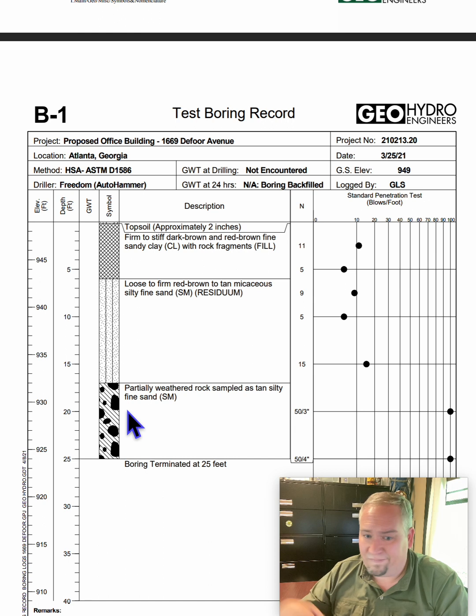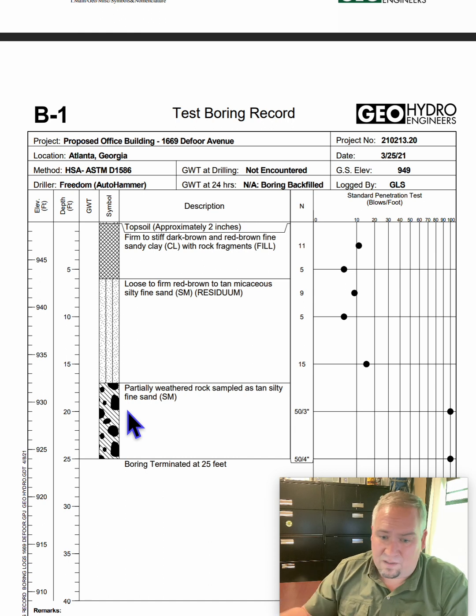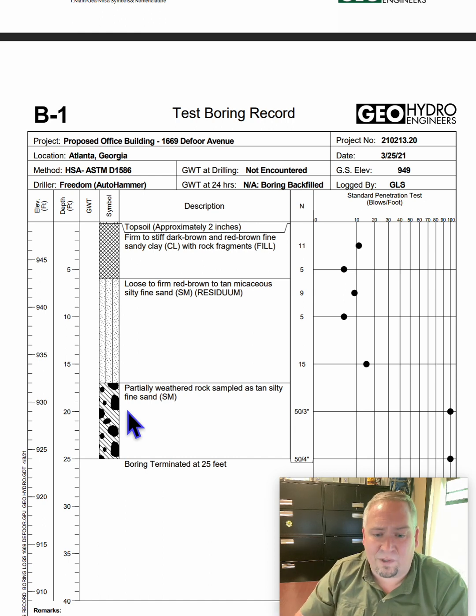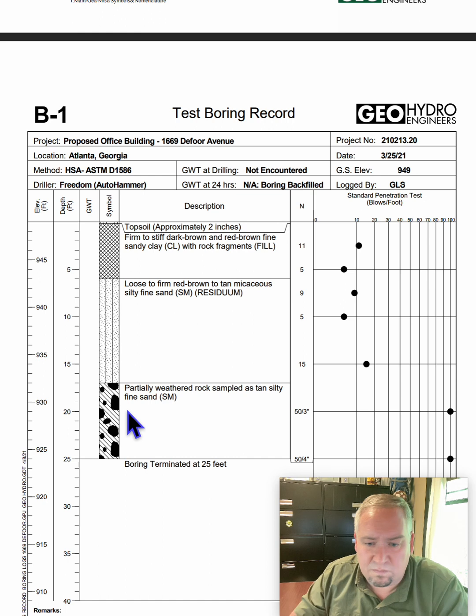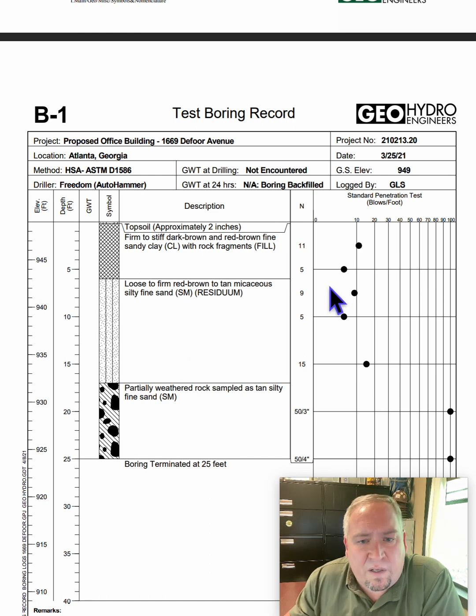So once we hit it, we can reach over there and grab the hammer. Geotech says, yep, that's the rock we thought it was. Superintendent says, yep, we agreed upon it. Start the time clock, sign your paperwork, get to rolling. Doesn't have to wait a day or two to get answers. Okay, moving across here are N values.